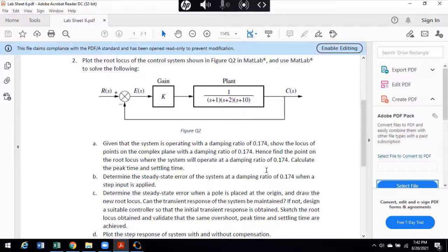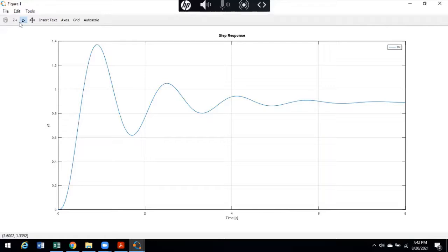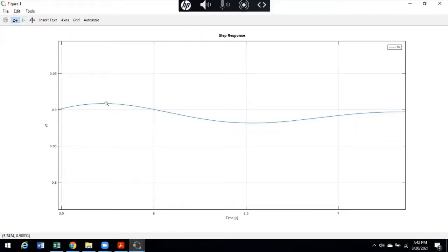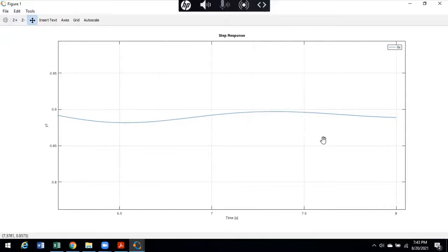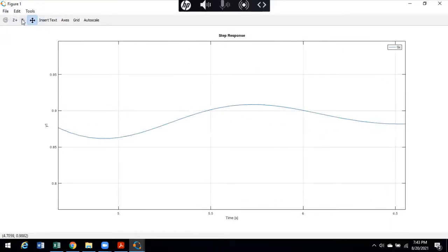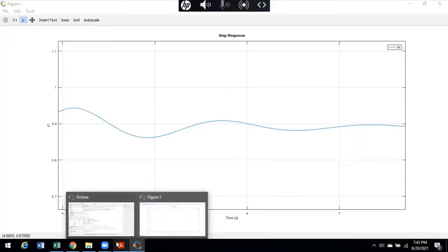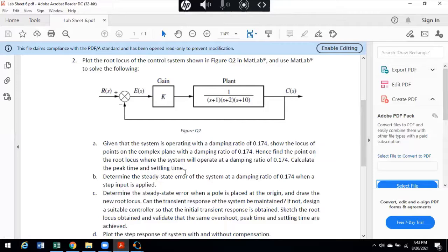And then based on that, you can look at your graph. You can zoom in where it is stabilizing here, and see at what point it reaches its final value. Let's say the final value it is tending to is 0.9, just to take an example. You find that it is still oscillating, but you can get a steady state value. Once you have a steady state value, you can determine at which point it stays within 2%, and then take that time as the settling time. So this can be easily done. Okay, so this part is okay.